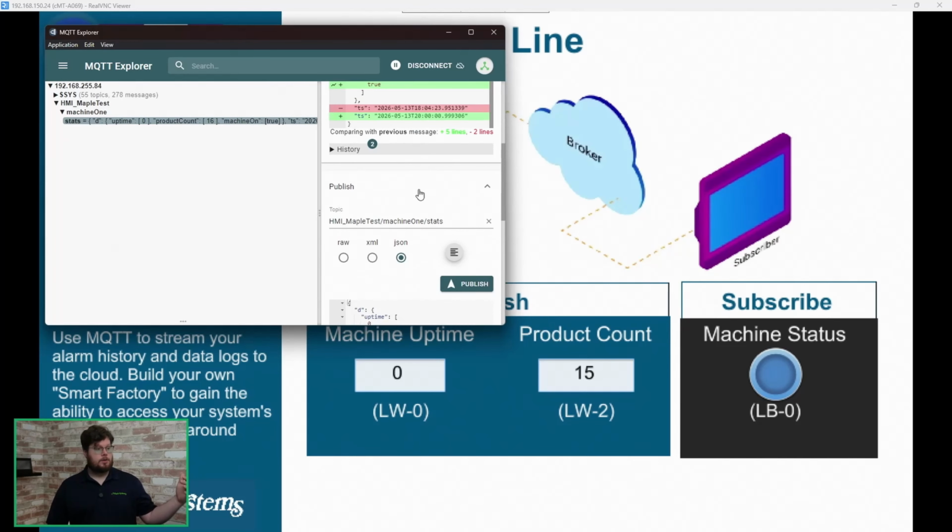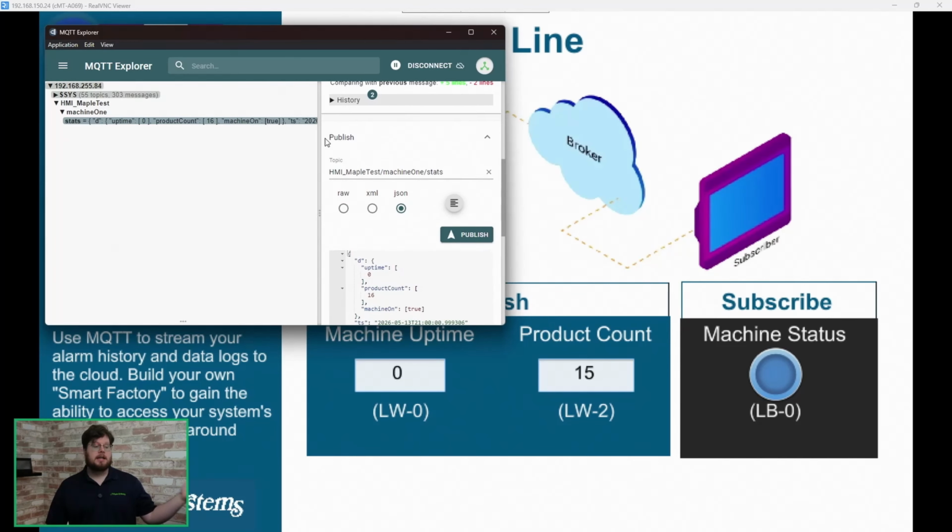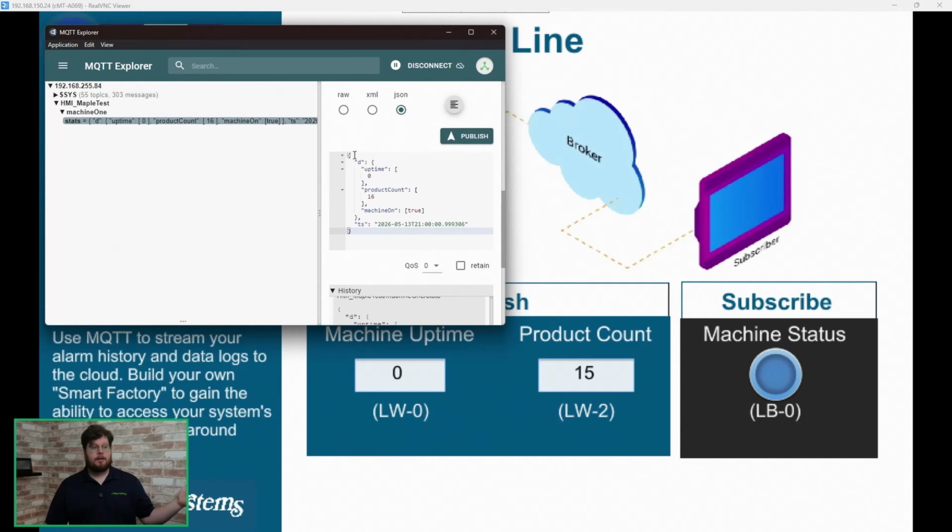Now I'm going to use this MQTT Explorer to publish a value to the broker. I've already gone ahead and set up the JSON there for it. Importantly, it's going to be this machine on tag, which, as you know, we set as a subscriber tag on the HMI. So I'm going to go ahead and push this, and then we should see this bit lamp turn on. There you go. And that about does it for today.